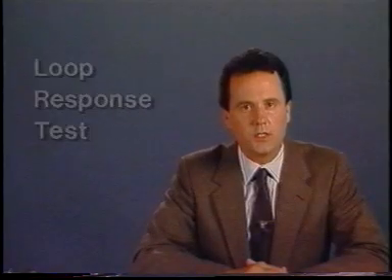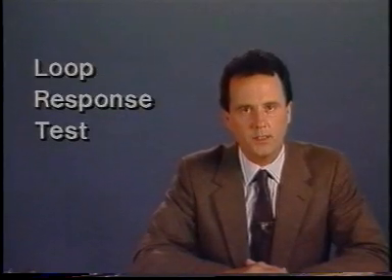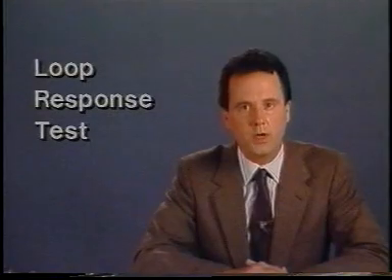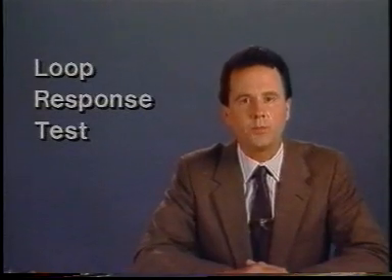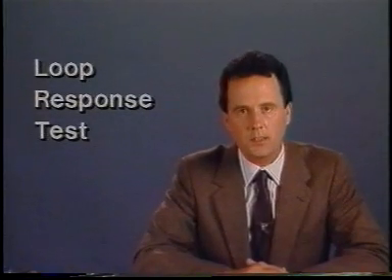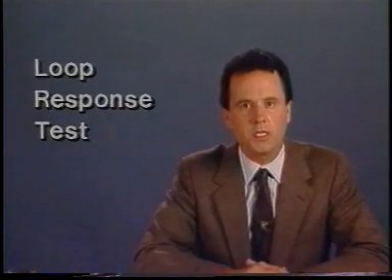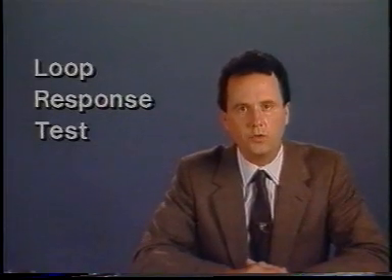As we discuss the nature of control loops, we need to identify the components involved and discover how the loop responds to change. We do this through conducting a loop response test. In fact, since a change in the process load will bring about a change in the process gain and time constant, it may be necessary to conduct response tests at differing loads.